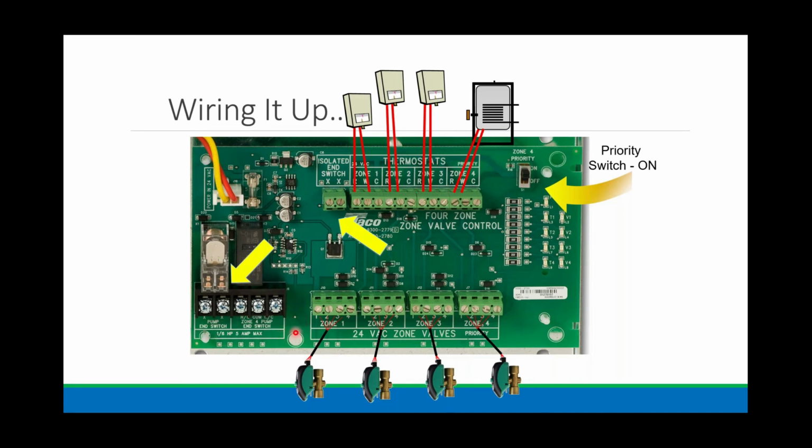And then what's next is at the bottom where the zone valves are, and I give you 4 terminals. 1 and 2 is your motor, 3 and 4 are your end switch. So if you're talking Honeywell, 1 and 2 yellow, 3 and 4 red. If you're talking 571s, terminal 1 to 1, 2 to 2, 3 to 3. If you're talking the Taco Zone Century, we label 24 volts right on the zone valve head. That goes to 1 and 2. We label end switch. That goes to 3 and 4.